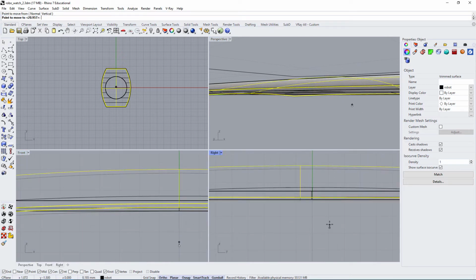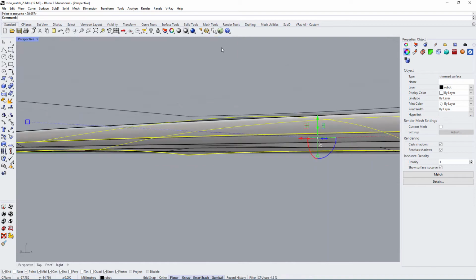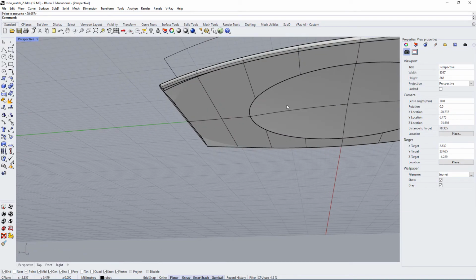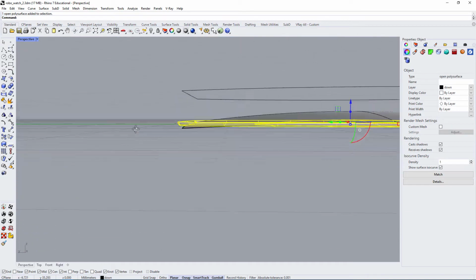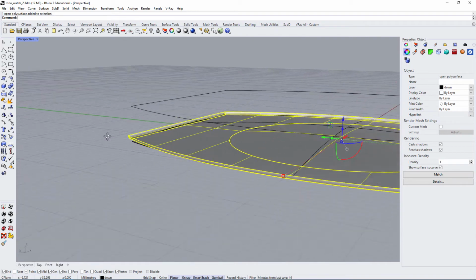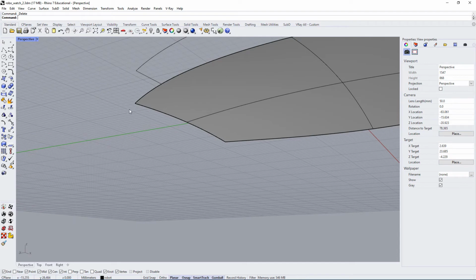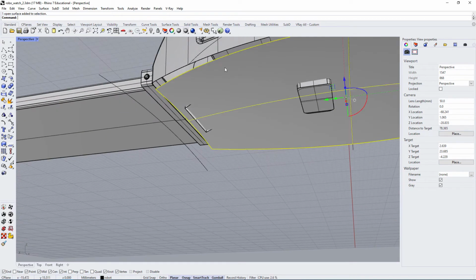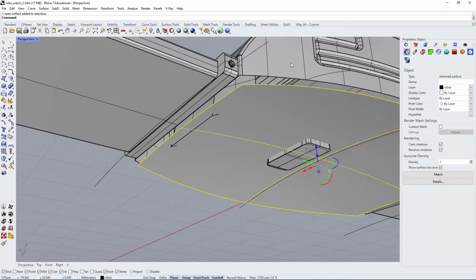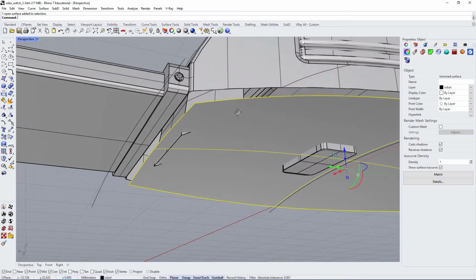We'll move this up just a little. And that's it. So now we can just delete that. You can see if you've done this correctly, when I show all of the other surfaces, I should get a large surface and then a large gap in between the surfaces.